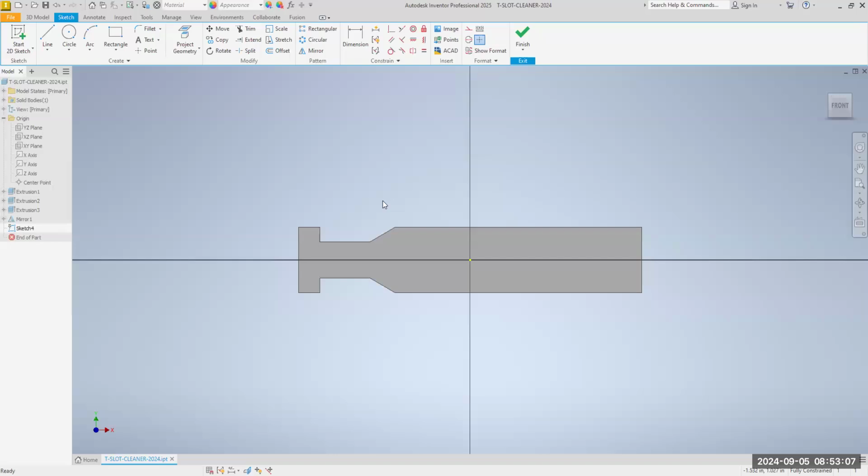What I want you to do now is go to circle, select circle, center point. Now watch. I'm just going to put that circle right there, just like that. Mr. Morris, that looks nothing like the circle on the thing we're going to be making. You don't have the drawing in front of you. You might if you brought it back with you today. So we need to properly locate the center of the circle, and then we need to change the diameter of the circle.